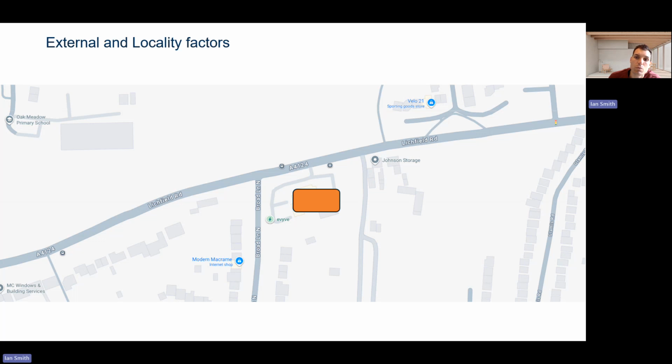So we need to monitor our construction activities, and specifically things like noise, dust and plant movement and how it could affect the public. So our site layout, as we'll see later, has been designed in such a way to remove risk or higher risk pieces of machinery and storage as far away from residential properties as possible, and our site security and things like our dust and noise suppression and working practices are going to be controlled in order to reduce the impact on our domestic neighbours.